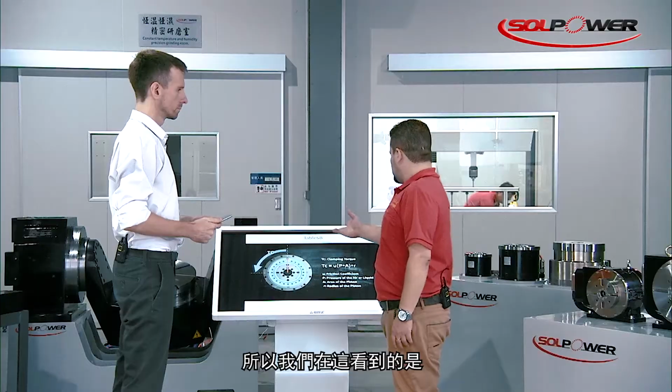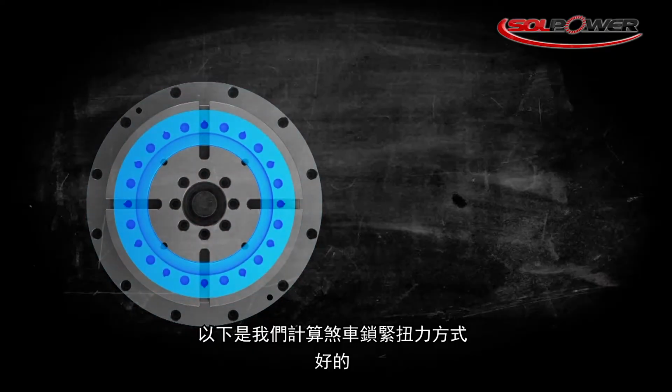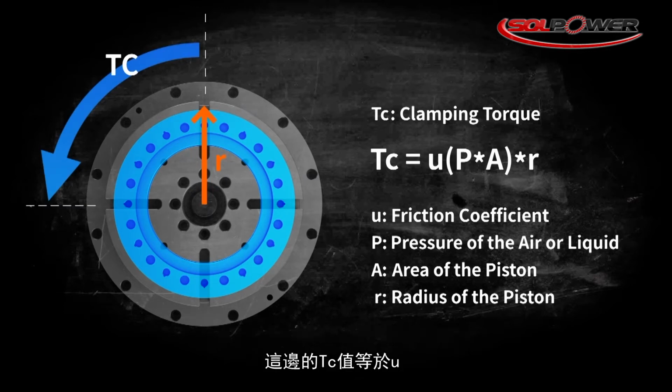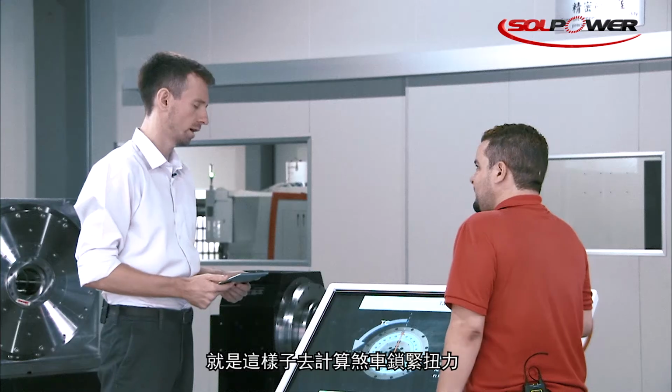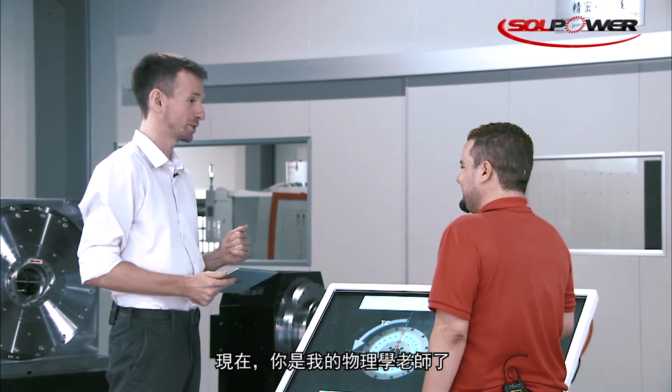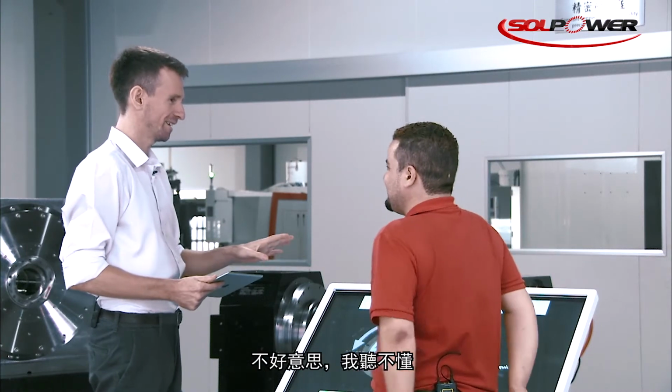So as we see here, that's the way we calculate the clamping torque. Here, Tc is equivalent to mu, which stands for the friction coefficient, multiplied by P, the pressure, A, the area of the piston, and multiplied by R, the radius of the piston. So that's the equation for how you calculate the clamping torque. Yes. So now you've basically turned into my physics teacher. Sorry, I don't understand anything. It has to be said, yes, sorry.